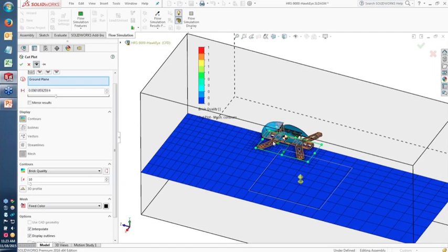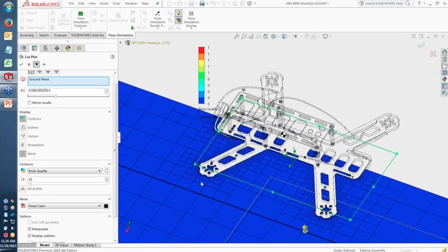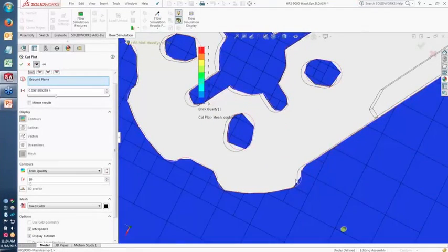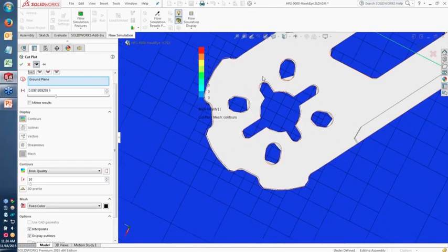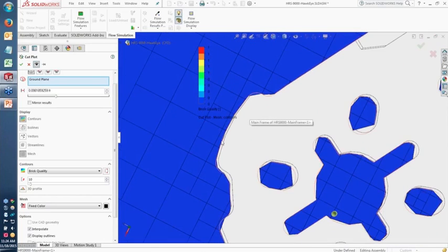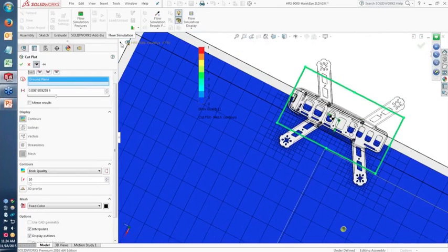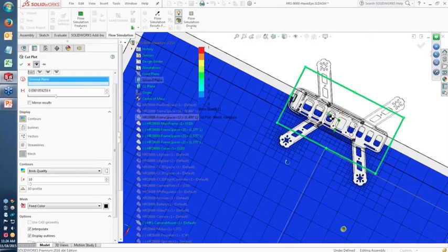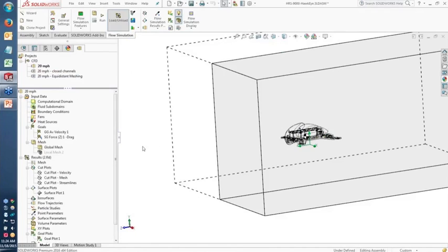And if I just turn on the preview here, for example, level 0 is good, which means that the cell itself was properly trimmed, and the boundary here of the partial cell itself is representative of the original geometry. And you can see on this plot that it shows you the actual boundary sort of overlaid onto what the original model looked like. So you can tell how closely the cell itself is approximating that curvature. And if there were any cells that for whatever reason didn't get trimmed properly, those would show up in other colors. So again, that's related to making sure you have a good mesh, more on the results side.